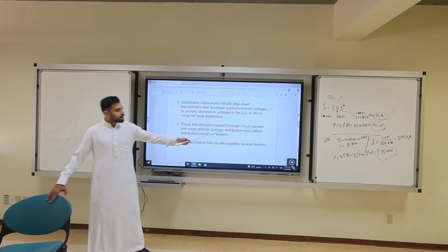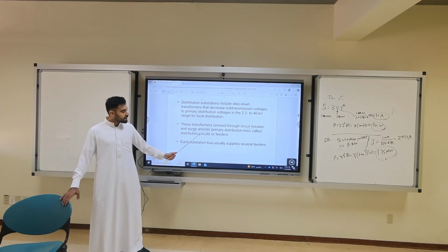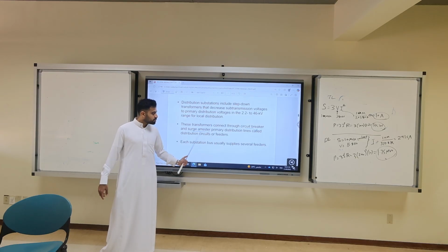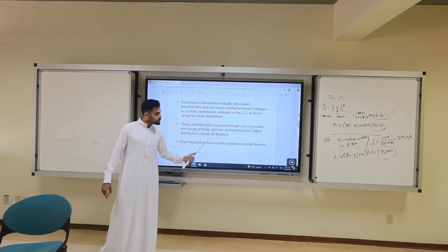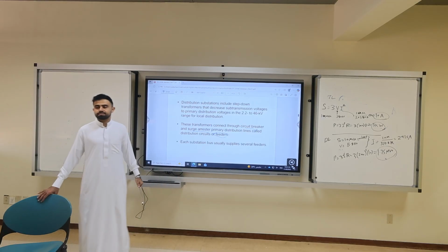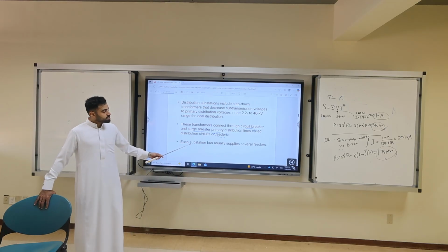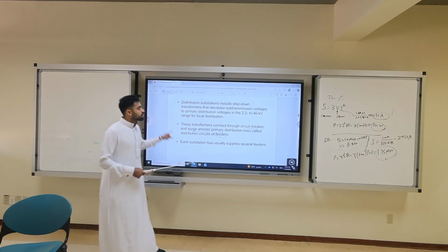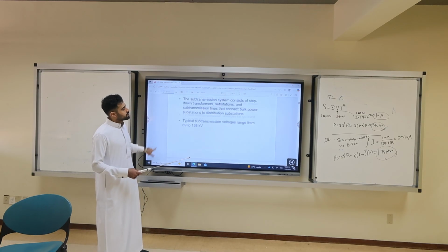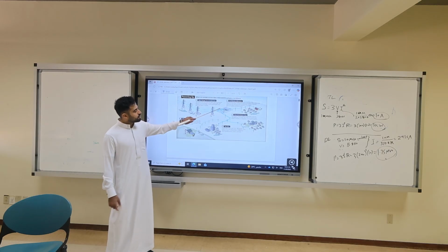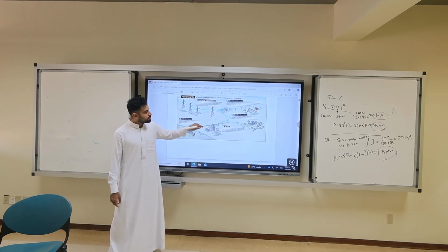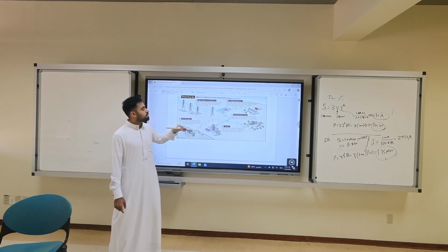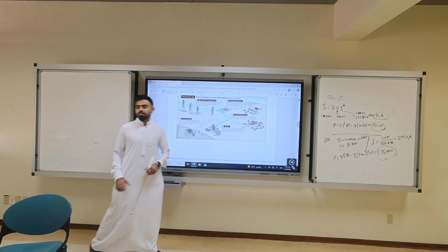The distribution lines are also called distribution circuit or feeder. Two names: distribution circuit or distribution feeder. Feeder is the most dominant name. Each substation bus usually supplies several feeders. Look at this substation. We have here one feeder, feeder 2, this is also feeder 3, 4.